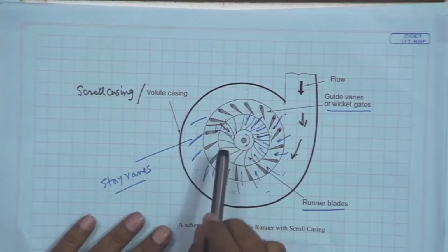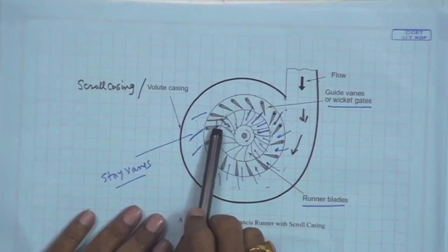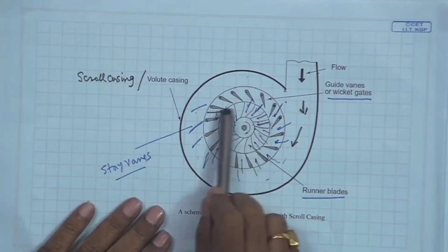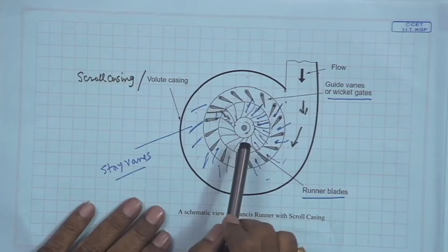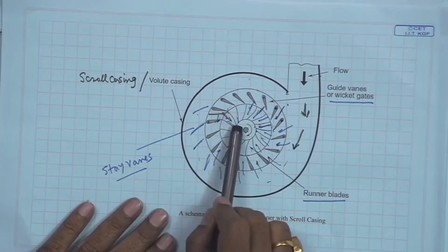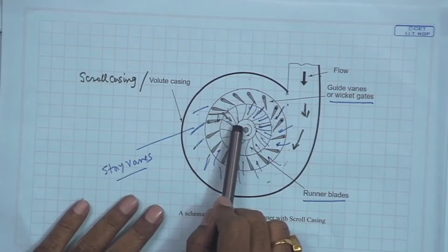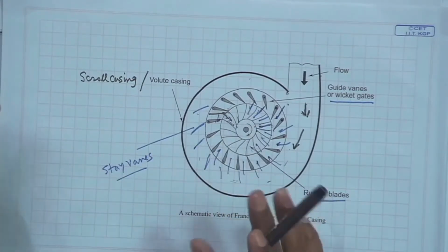Now, one important thing that we already discussed is that this reaction turbine is efficient at low head. That means, if it has to run efficiently at a lower head or a higher specific speed, then to develop considerable power, it has to admit a large amount of flow into the turbine. That means the flow rate has to be high if the head available is less.